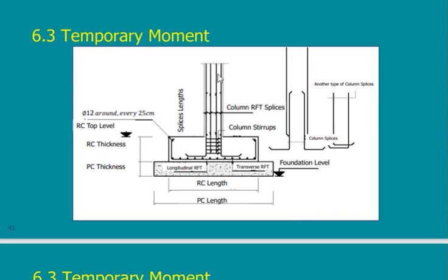As you see, my reinforcement will be similar to an isolated footing without moment, but the real difference will be in the amount of steel. It will be a very high amount of steel, but the column will be in the middle. From here I will not know that I have a moment, because it's a normal column in the middle, it is not shifted.